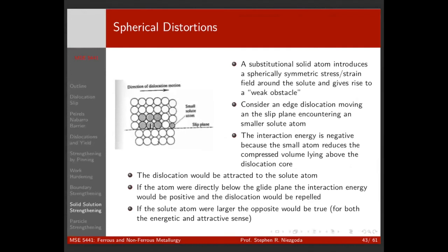And then we can look at what those actual interactions look like. But basically it comes down to Gb squared, right? If we put a stress field around it caused by a size distortion, or change the nature of the bonding when a dislocation hits it.